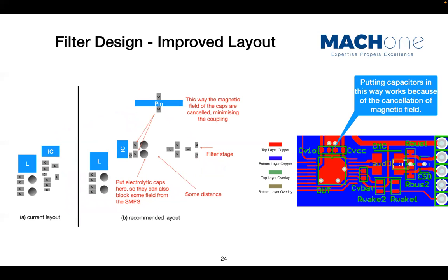Well, three reasons. First, electrolytic capacitors store much more energy, right? For higher power switch mode power supplies, you can't just rely on ceramic capacitors to provide that energy. Simply, you cannot. The second is that electrolytic capacitors have internal ESR, and this ESR is higher than in ceramic capacitors. People think it's a bad thing, but actually in this case, it damps the system.